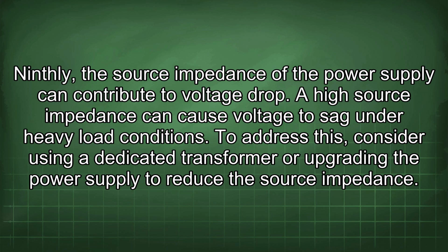Ninthly, the source impedance of the power supply can contribute to voltage drop. A high source impedance can cause voltage to sag under heavy load conditions. To address this, consider using a dedicated transformer or upgrading the power supply to reduce the source impedance.